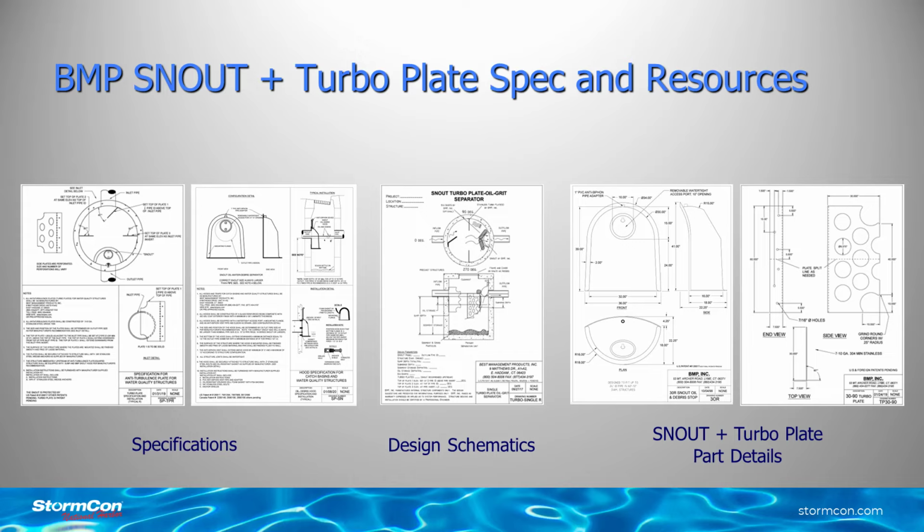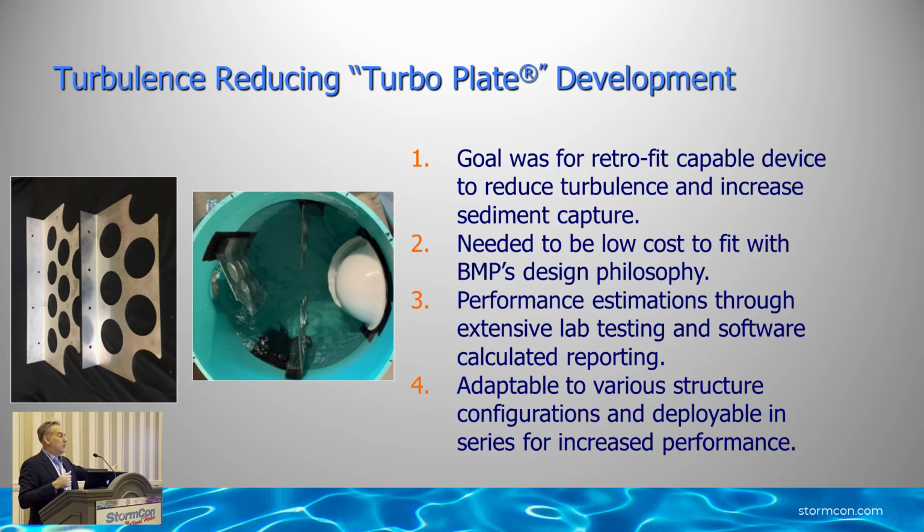So what happens is, again, the hood's a very simple concept. We wanted to come up with another simple concept that we could use to retrofit structures. So the idea to us, how many people are aware of a sawtooth weir on top of a treatment plant intake, right? The whole goal is, it's the same amount of water flowing over it, but it's a lot more area. There's a lot more vertical space that it covers. If you stretch out that sawtooth weir, you see that the water was flowing over 2 times the distance. So because you're flowing that water over a greater area, the velocity reduces.